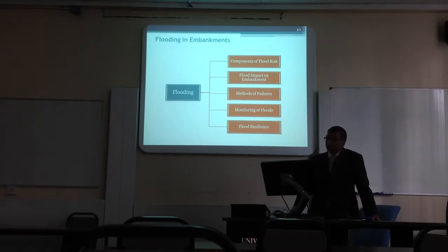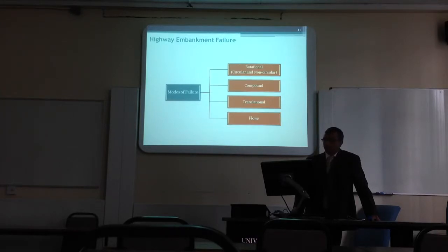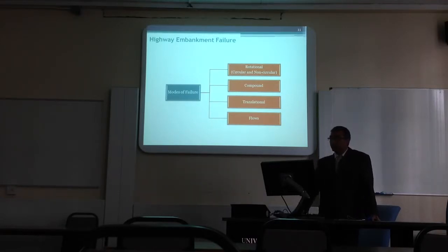So flooding in embankment, how the flooding occurs. There are components of flood risk, which are the source, pathway and receptors. The flood impact on embankment is important to be studied, and then method of failure, monitoring of floods, and then flood resilience. So the modes of failure, what are the modes of failure? There are four basic kinds of failures, which are rotational, circular and non-circular, compound, translational, and flows.